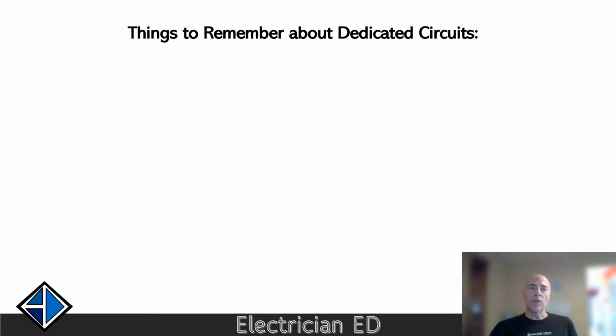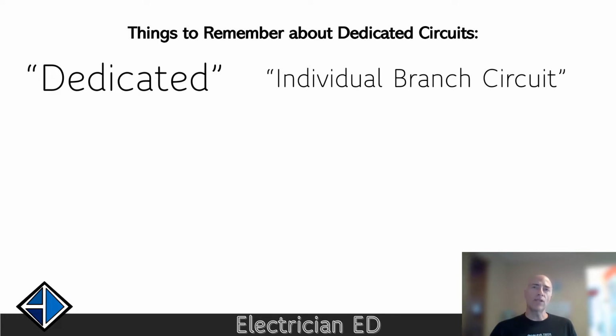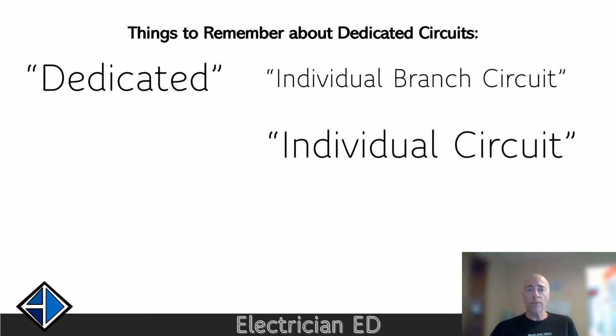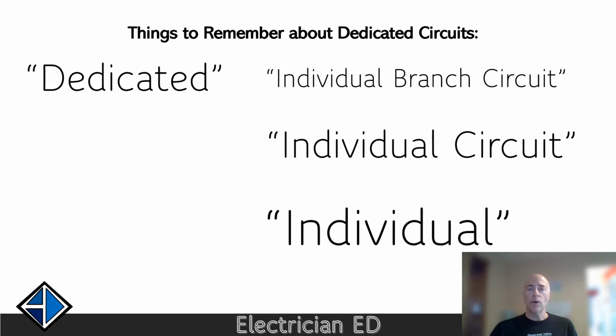So what do we mean when we use the term dedicated? The NEC never actually uses that term. Instead, the closest thing to it in the code is individual branch circuit or individual circuit sometimes. You'll see that often in manufacturer's instructions for installations, or even just individual. Usually dedicated and individual mean the same thing, but it doesn't hurt to double check terminology with anyone that uses it to make sure you're both on the same page.